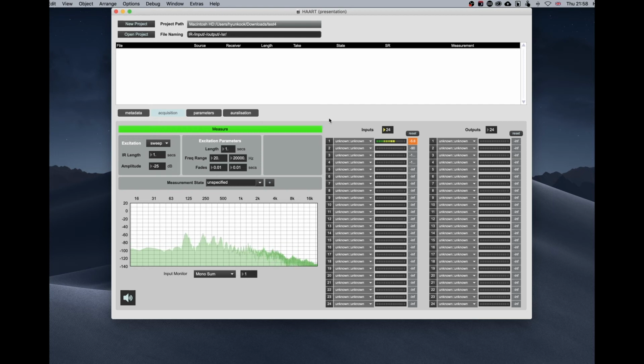If you understand the nature of the exponential sine sweep method, it involves the original sweep and the recording of the sweep in the room, and then you have to convolve it with the inverse sweep, which is called the deconvolution process. And there is also some necessary equalization process involved at the end. They're all done within this all-in-one toolbox.